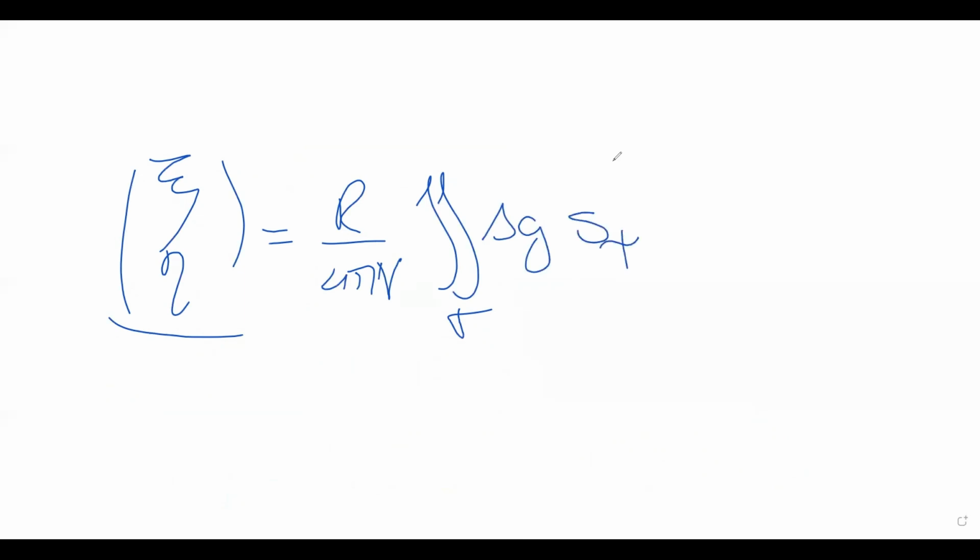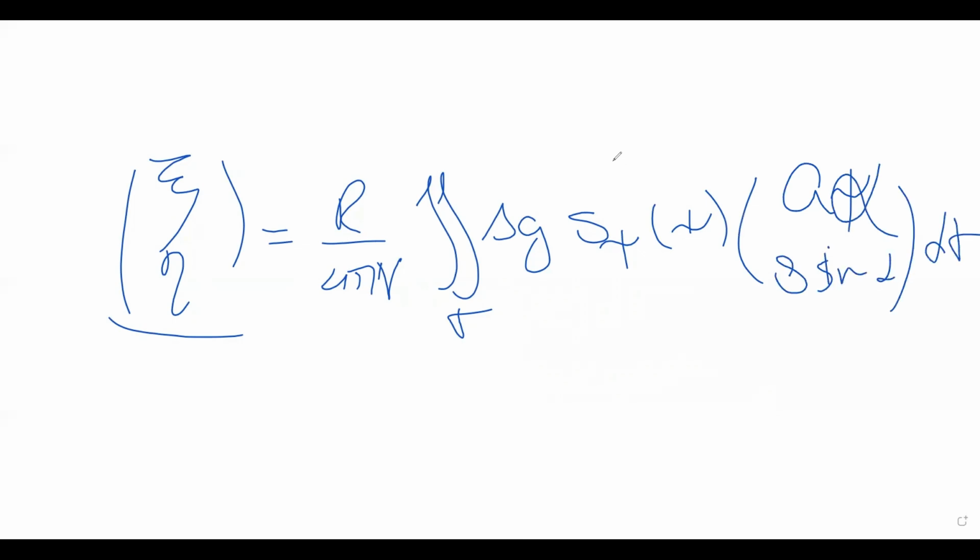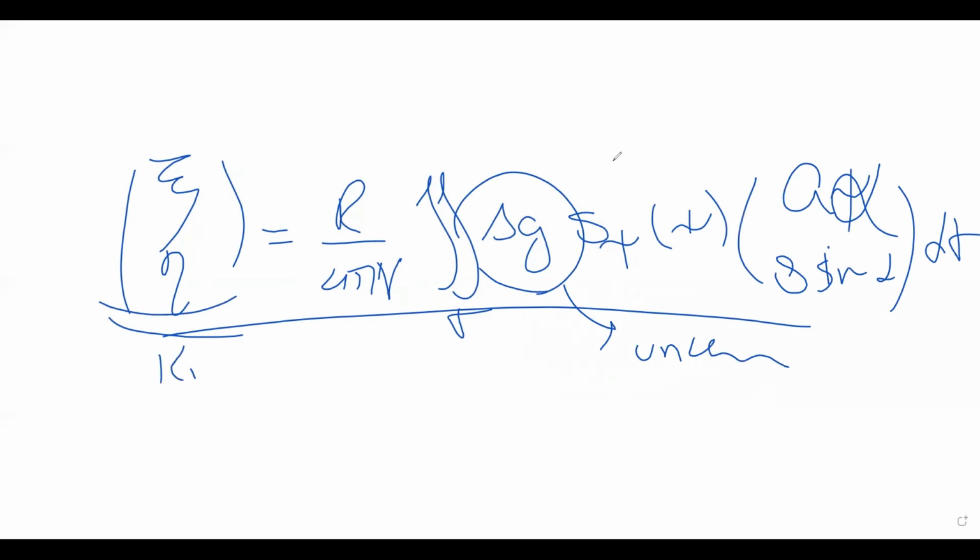So now assume that I have computed the deflections of vertical directly from the marine geoid. Simply I can write this as an integral of gravity anomaly times the derivative of the Stokes function with respect to psi, times the derivative of psi with respect to phi, and this is cosine alpha, and this is sine alpha. Then again you have an integral equation. Here you have unknowns, and here are knowns. You can discretize this integral and solve it numerically by a regularization method to get gravity anomaly.